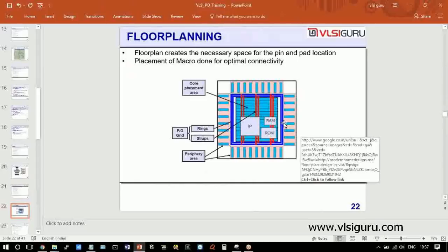And in industry, it is that way. Keep that in mind. Your GDS is all about that. And everything has got a reference also. The reference is always LL. LL is nothing but lower left. We will go through it. Whether it is a chip reference or a cell reference or an IP reference or a macro reference, it is lower left.